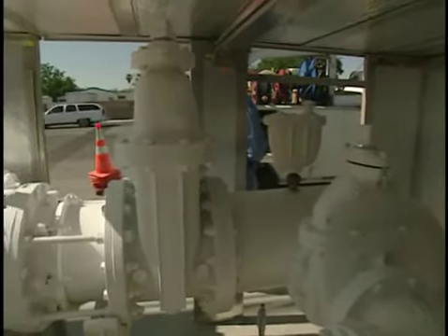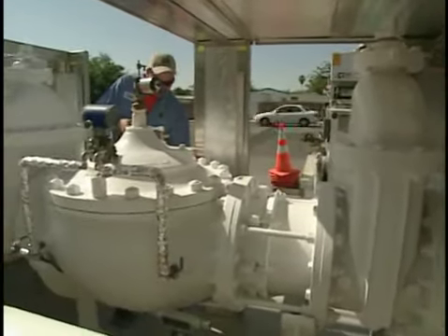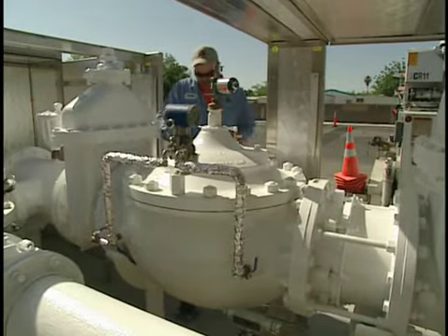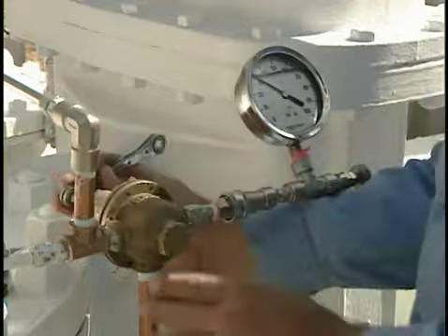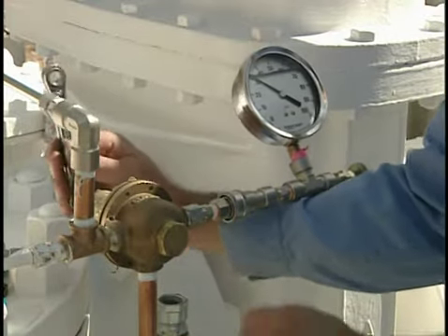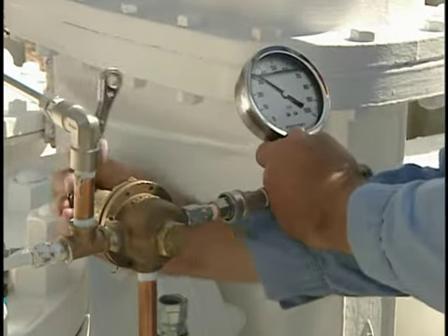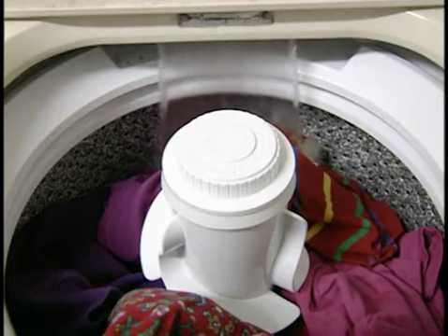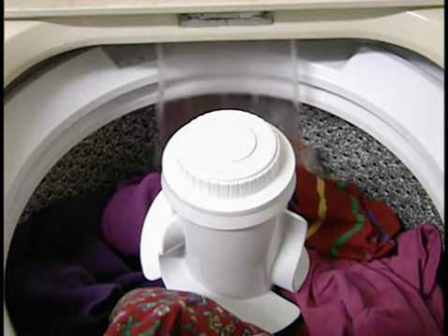Pressure regulating and relief valves are designed to withstand the high pressure forces that are created when throttling the flow of water. It's generally desirable to maintain pressure to residences and businesses at less than 60 psi. Pressures above that are more likely to cause plumbing failures, leakage, and reduced life of appliances.